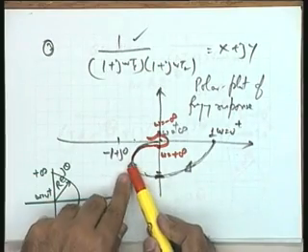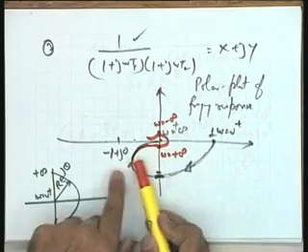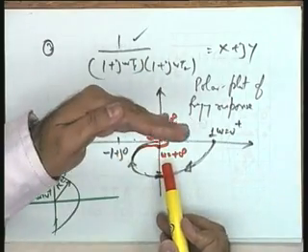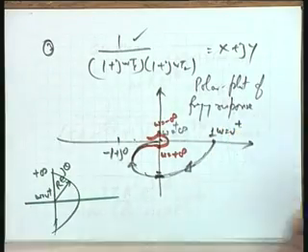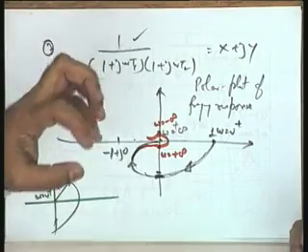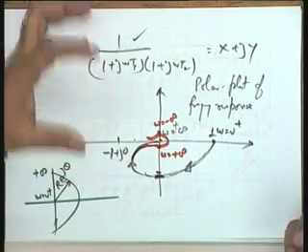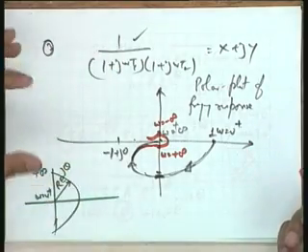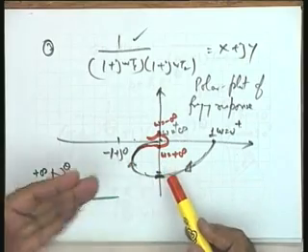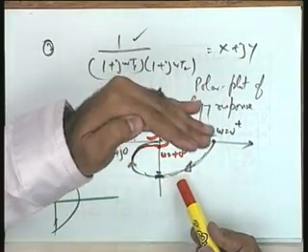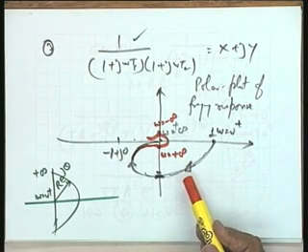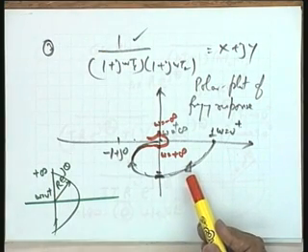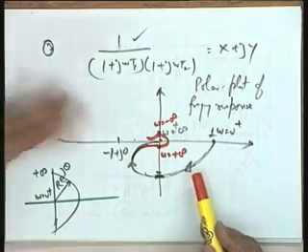On this contour, the angle tends to the origin asymptotic to minus 180 degrees and comes out of the origin asymptotic to plus 180 degrees. It is a mapping of s equal to r e to the power of j theta, because the theta angle is also important, and the theta angle shows up this way, that you enter the origin asymptotic to minus 180 degrees and come out of the origin asymptotic to plus 180 degrees. Okay? I hope this point is clear as far as the mapping is concerned.